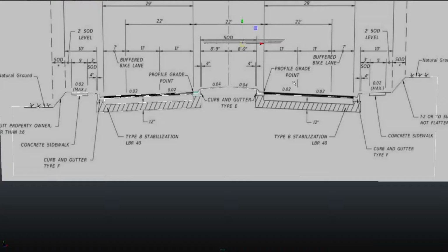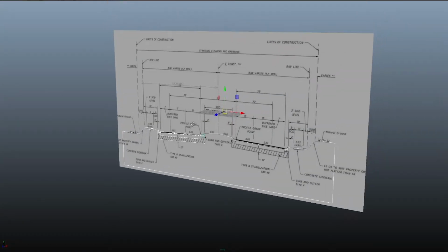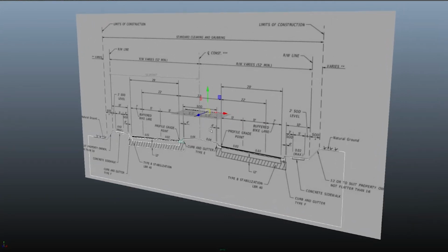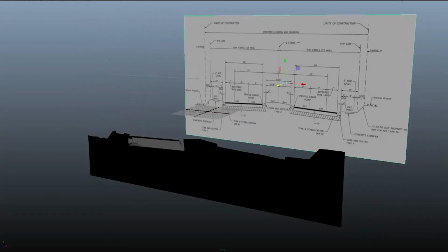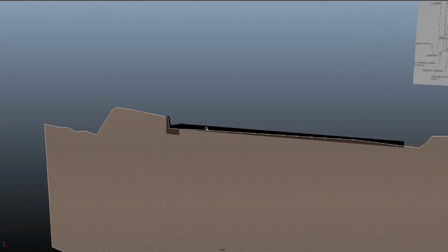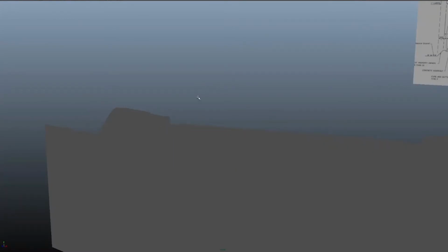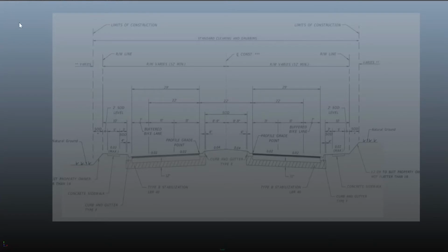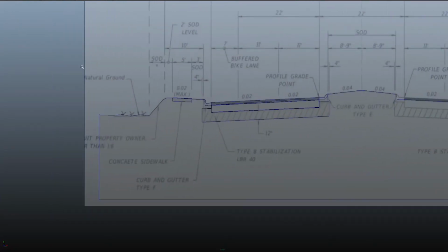Now that this is done, we have our basic shapes here. If you go to the 3D window now, it's kind of hard to see because it's literally on top of your plane, your design plane. So take this plane and just push it out of the way, move it way back. And then I like to turn the grid off because that just tends to get in the way. And I'm going to go ahead and delete those dimensions, those measuring tools from earlier, just get that out of the way. Now this is black just because the normals got reversed. So if that happens, just reverse your normals, not a big deal. Only takes a quick second. So I'm going to do that. Let's go ahead and turn on wireframe unshaded so you can see the work that you've done.